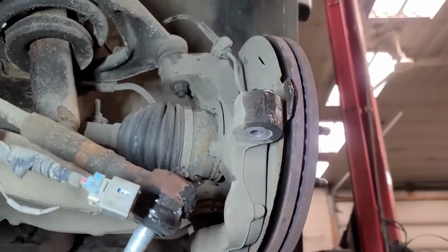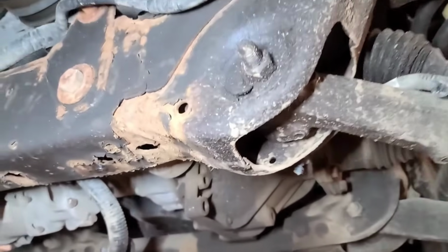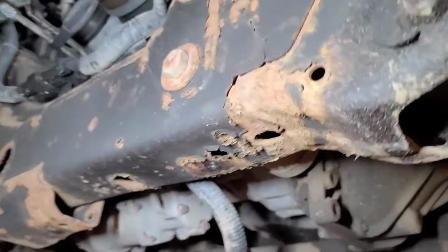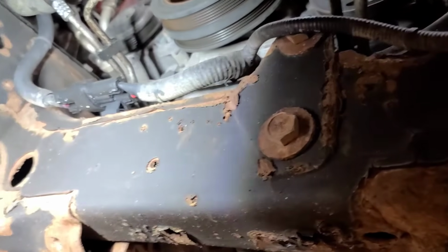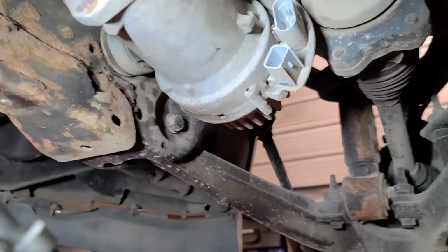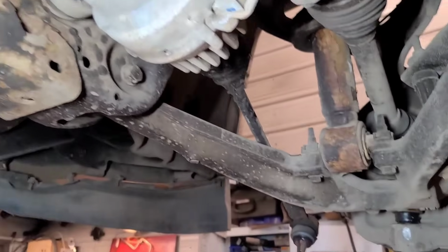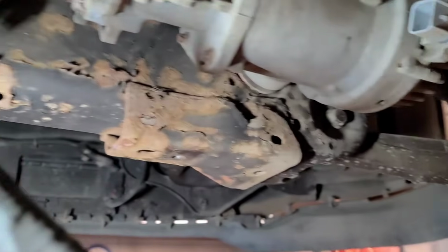So remove the front wheels, disconnect the outer tie rod ends, unclip the wiring harness from the steering gear. Now there are 3 bolts, these 2 here and one on the right side through that hole, that hold the steering gear in there. And it looks like it's going to come out by moving it towards the right side until this tie rod end comes out of that control arm, and then it should drop down and go to the left.